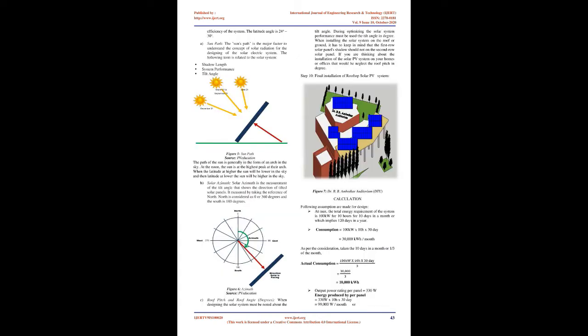Step-by-step design processes of PV solar panel on rooftop. 1. Adding location using Google Maps. 2. How to build a 3D version of any selected site. Step 1. Getting started, open SketchUp. Step 2. Acquire imagery and location.